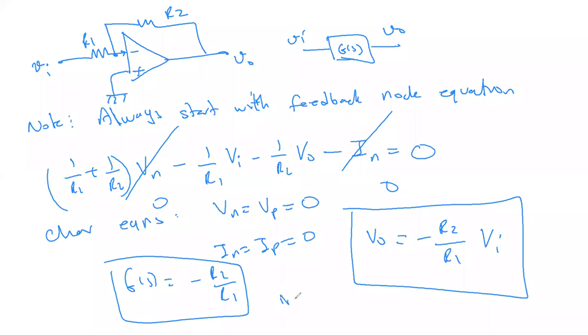It's called an inverting amplifier. By making R2 greater than R1, we get the amplification of the input at the output. And with the minus sign, we are changing the polarity of the input signal. When it is positive, it will become negative, and vice versa. This is one of the most common uses of op-amp amplifier circuitry. Probably most of you have seen it.